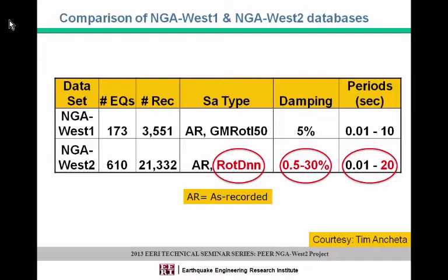One other change that we made, and again, it's not a big deal, but it's doing something better, is the so-called intensity measure. Traditionally, like 30 years ago, each earthquake is recorded at a recording station, and it usually records 3 components. For the horizontal components, 30 years ago, we used to take the geometric mean of the horizontal components, which is the square root of H1 times H2. This was a while ago.